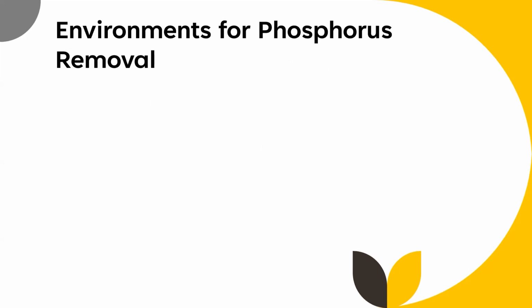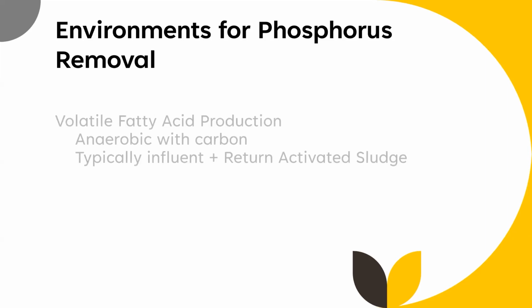The environments for phosphorus removal are different than for nitrate removal. I will note, however, if you are unable to drive nitrate levels down, your chance of having success at biological phosphorus removal is quite low.